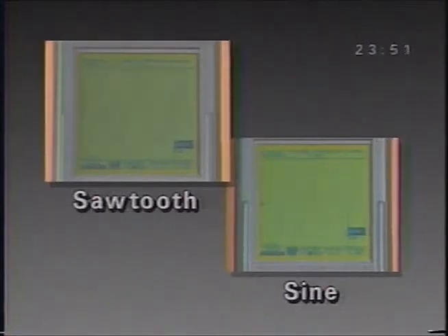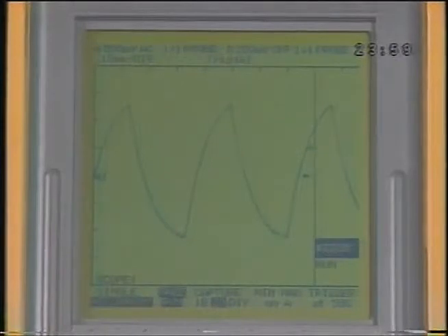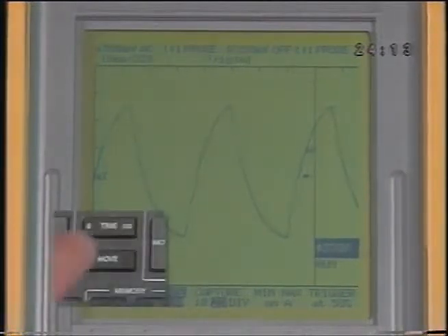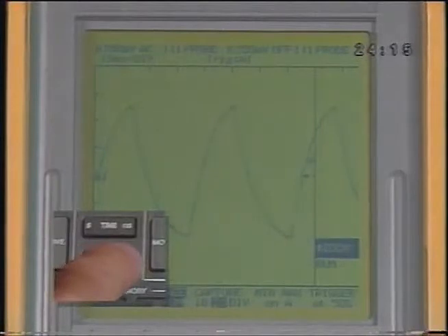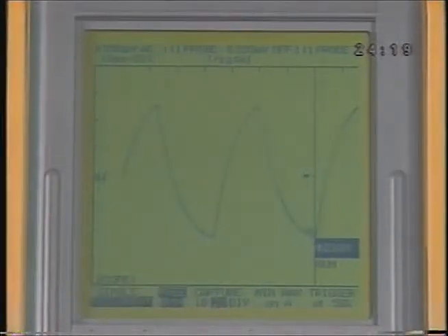Most of them, such as a distributor pickup or a permanent magnet vehicle speed sensor, will produce a more pointed waveform. These are still AC signals, but because they come to a point, their peaks are better suited for generating precise timing signals. You'll use this sawtooth waveform to see how adjusting the trigger level and slope changes the way you view these waveforms. Use Move to move the waveform 1 division to the right. That will make this exercise easier to see.